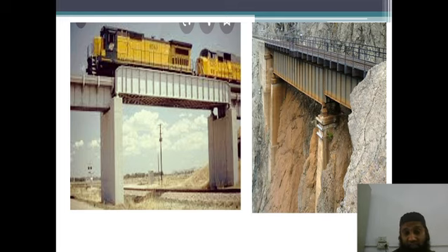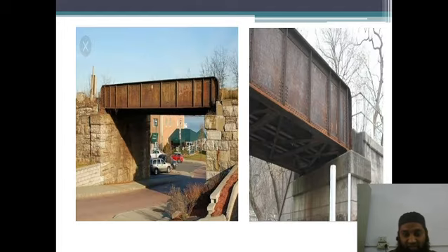So this is a very important structure, but it should be designed accordingly. If it is not designed accordingly, then there are high chances of collapse. And the other thing about structural steel members, as I had told you, the biggest problem or disadvantage is that it needs a lot of maintenance. Basically it needs maintenance against corrosion. If the structural members are not given maintenance against corrosion, then there are high possibilities of it yielding and thereby leading to collapse.